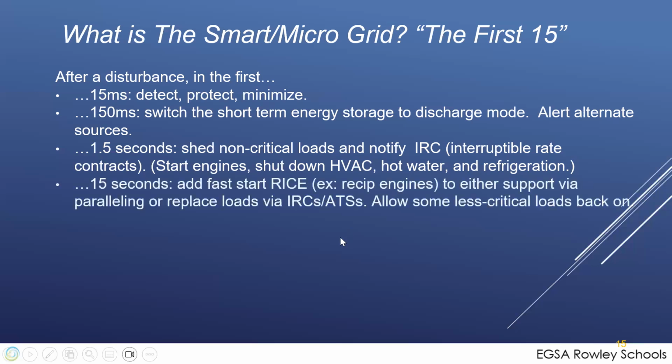Also, at this point, you can shut down all your HVAC systems and your hot water heaters. If you turn the air off in your office for 15 seconds, you wouldn't even know it. You shut off the hot water heaters, induction furnaces of any kind, and refrigeration. Take all that load off quickly in the first second and a half, and then at 15 seconds, you can start your RICE engines.